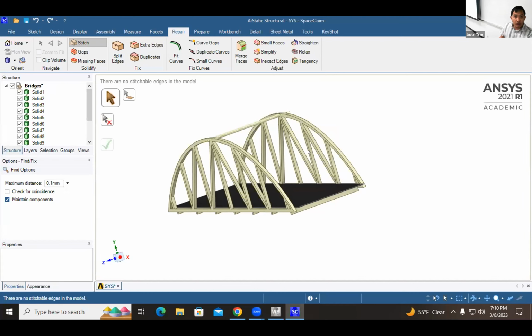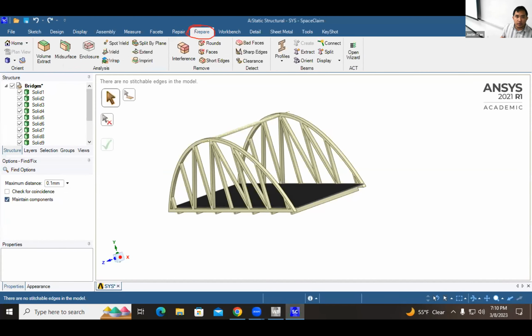Okay, so to transform a part of the model into shells, we're going to go to this button right here and click prepare. Let's go ahead and click prepare. And then the other thing you're going to click here is mid-surface. Remember, we talked about mid-surface on Monday. A mid-surface operation is basically, you click two parallel surfaces, and then it's going to create a shell in between them. All right, so let's go ahead and give it a try.